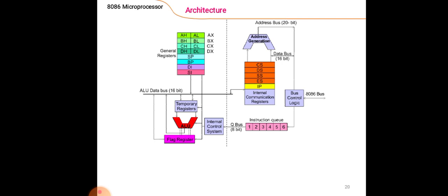Now I have previously explained that while executing the instruction inside the 8086, each instruction goes through 3 cycles, that is fetch, decode and execute. Fetching means placing or setting address locations for given command. Then decoding means converting command, that is assembly language, into machine level language.